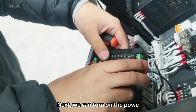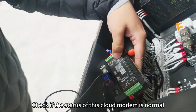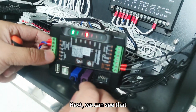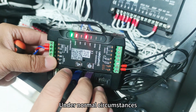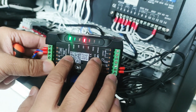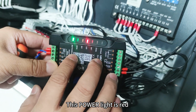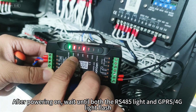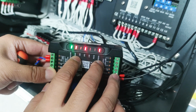Next, we can turn on the POW. Check if the status of this cloud modem is normal. Under normal circumstances, when it is first powered on, this power light is red. After powering on, wait until both the RS485 light and GPRS 4G light flash.